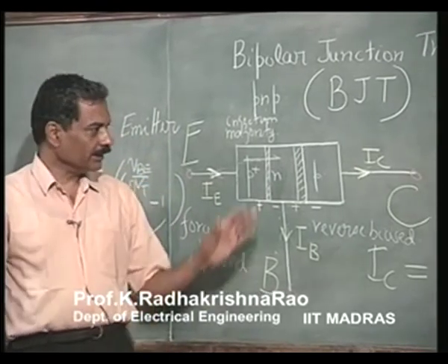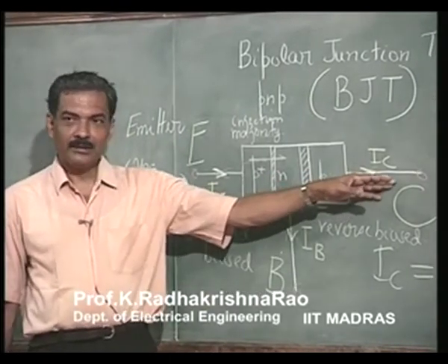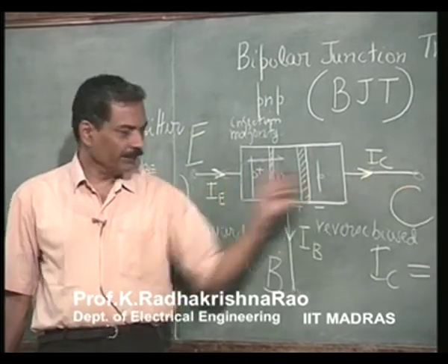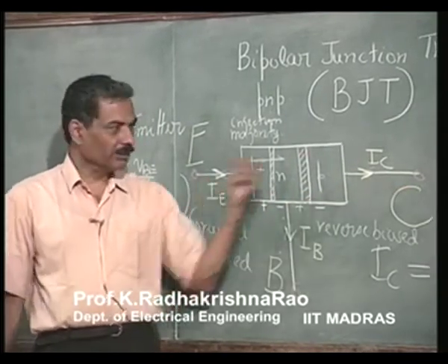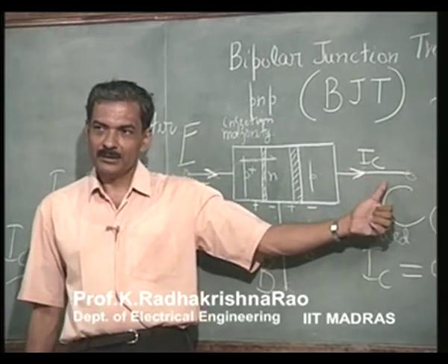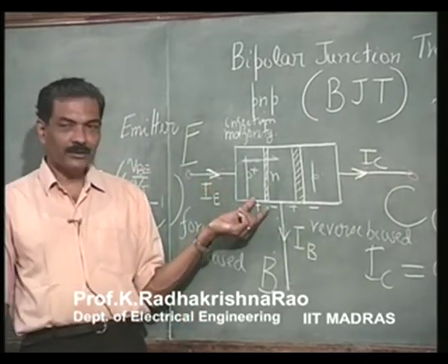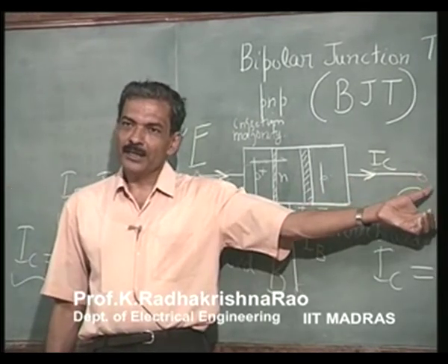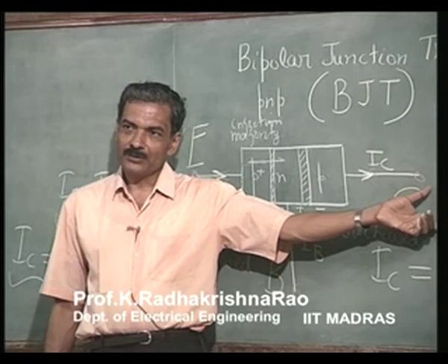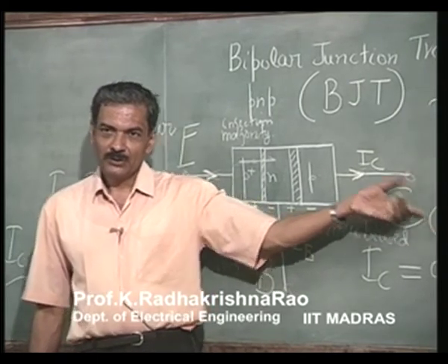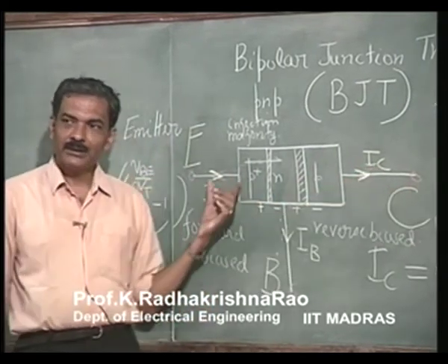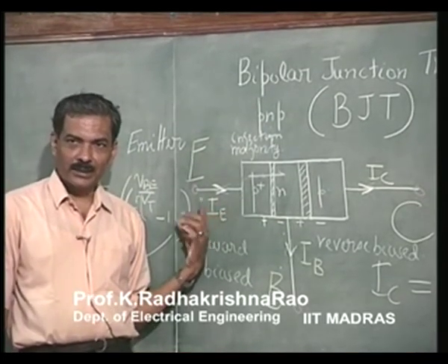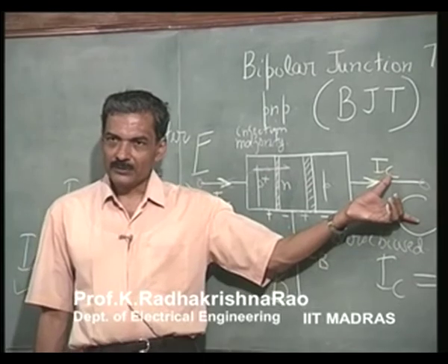So, this is a current controlled current source. If I have 1 ampere here, this will be 1 ampere. This 1 ampere is flowing into almost a short circuit, and it can flow into any load. So, you have forced an output current which is dependent upon an input current.